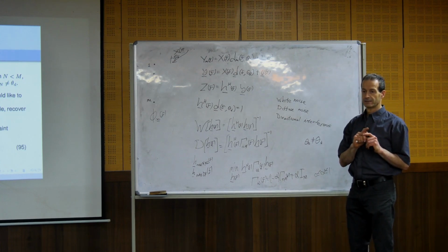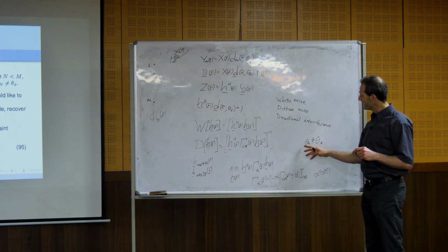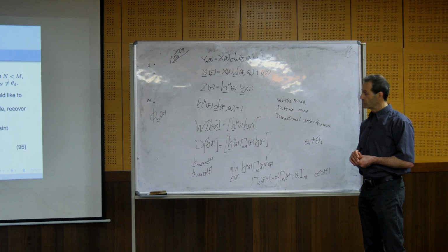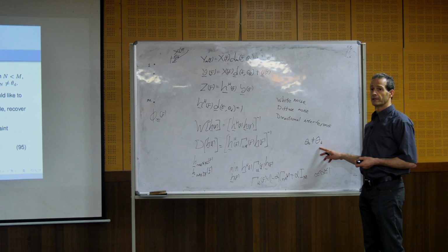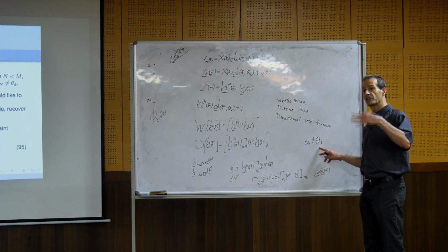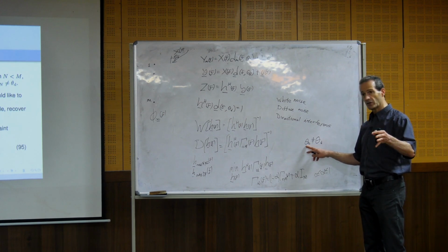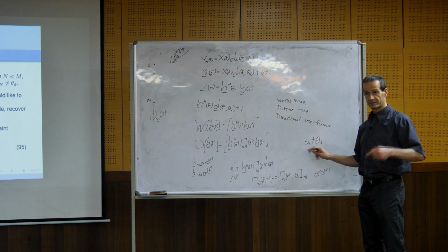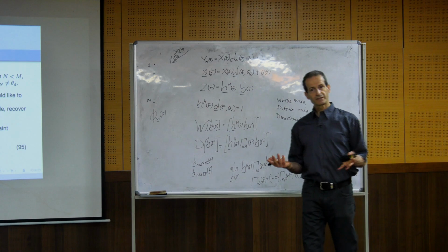Okay? On the other hand, if I design a beamformer such that it is robust to these differences, the robust beamformer, for theta d, the performance will be lower than the non-robust. But for theta 0, which is the error in the angle, it will be better than the non-robust. Okay? So, in other words, what does it mean?